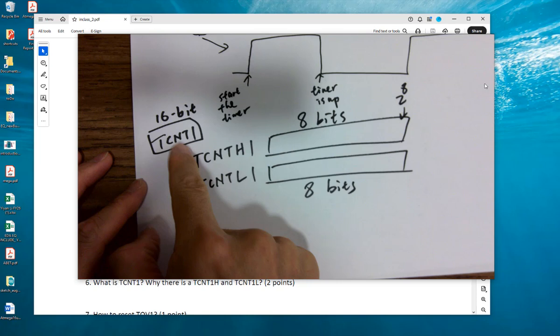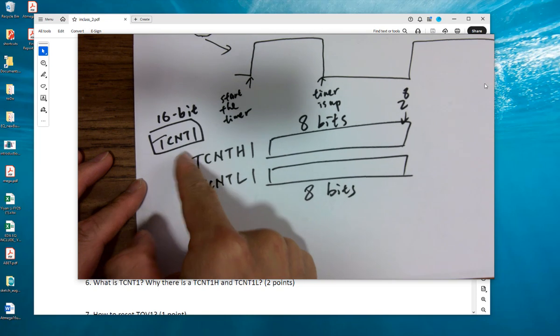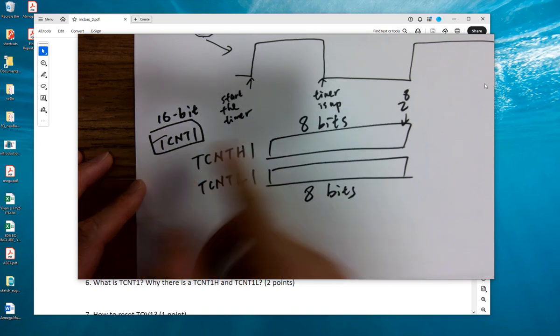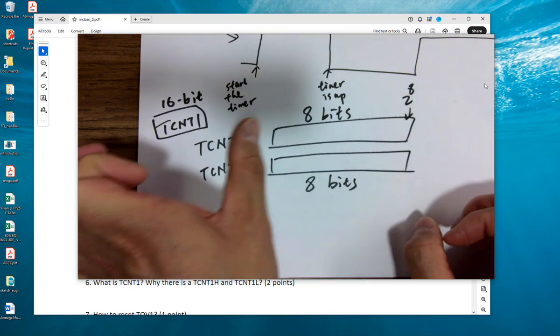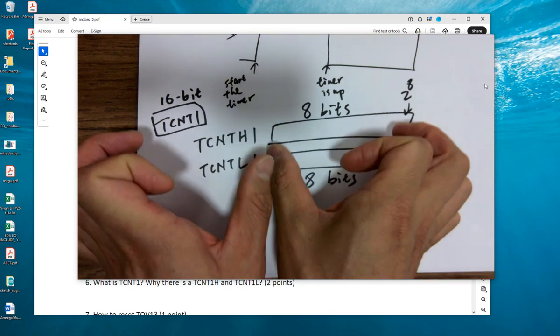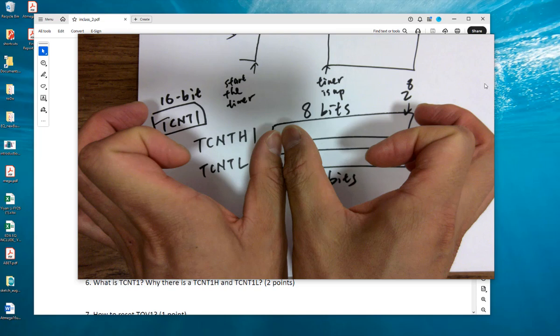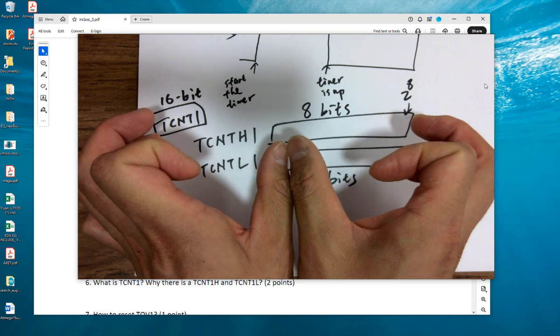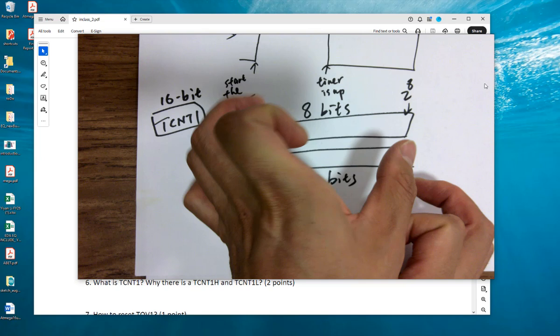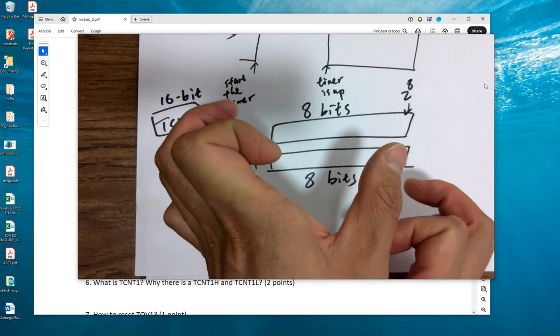However, whenever it forms this one, it's running behind the scene, it compiles it, it knows what's really happening. So it's actually shifting this one to the left by 8 bits, and then ORing this guy to it, right? So you are forming a 16-bit counting number instead of two 8-bit memory banks. You know what I mean?